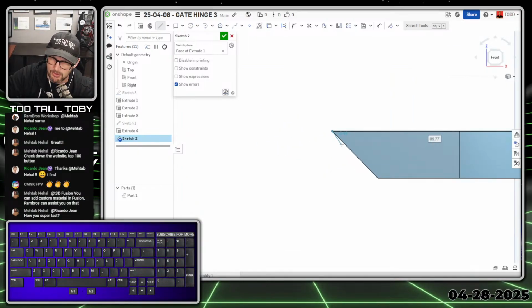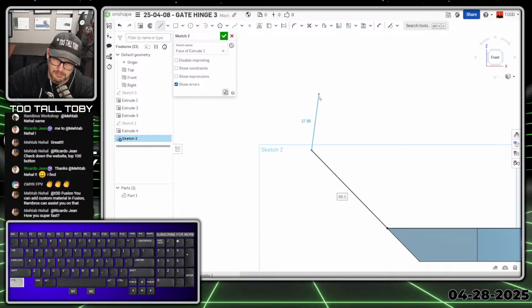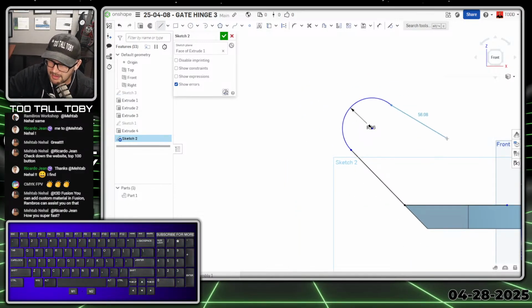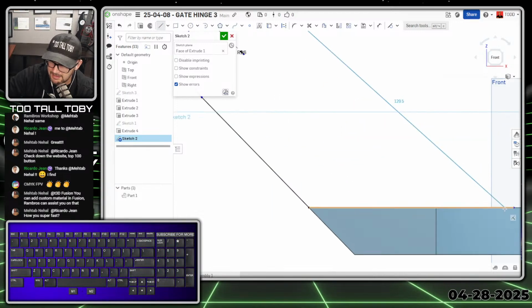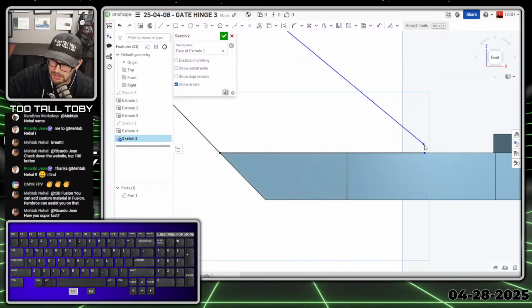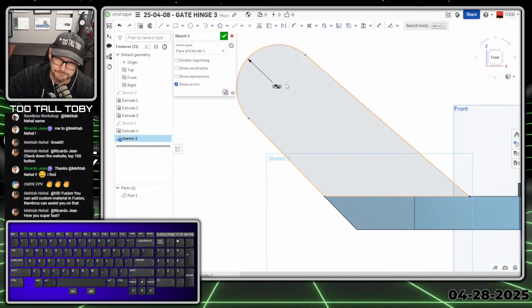And then in Onshape, if you hold your mouse over this line first, and then you move up in this direction, you'll see that you can get a parallel relationship. So we'll make that parallel, come back, touch the end point, come up and around, and we're gonna say this is gonna go around to a radius of 26. And then we're gonna continue our line here, make sure that we're getting tangent, continue our line down to here. Maybe I'll just drop it in space, and then I'll grab this endpoint and just connect it here. And that way those two become tangent.